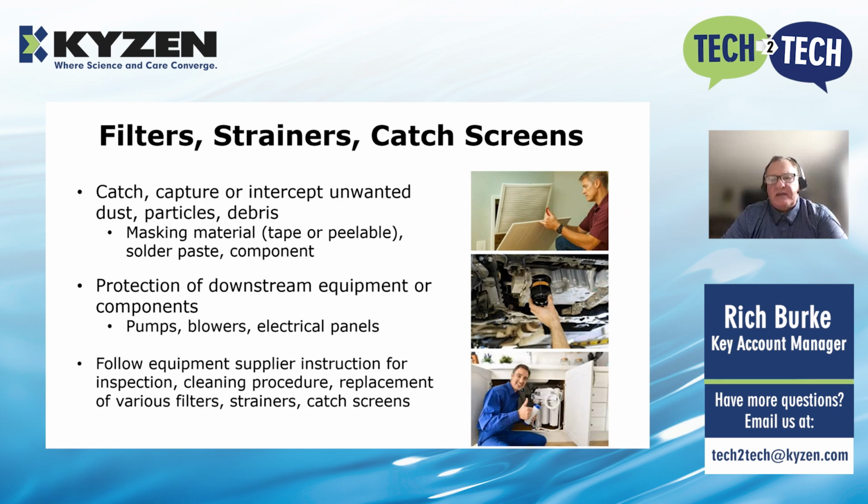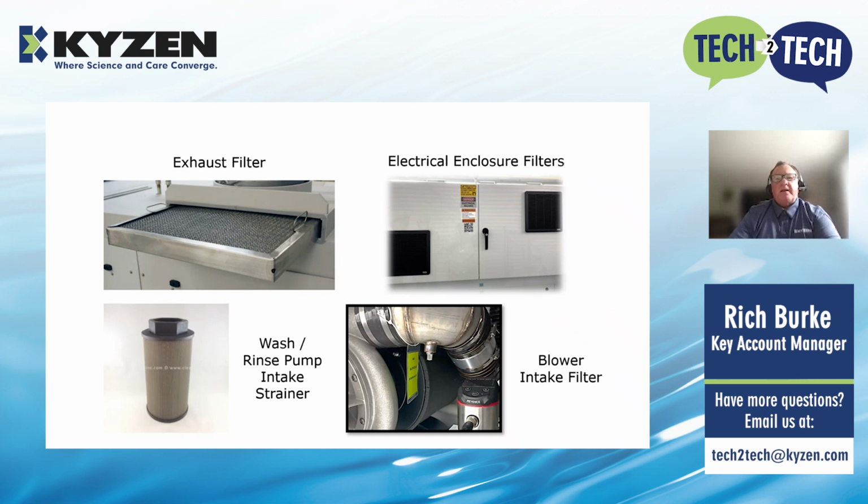So it's really a mechanism to protect our downstream components, and that can be our pumps, our blowers, electrical panels, ventilation system, for example. So, what I would say to this is follow the recommendation from our equipment suppliers in terms of the frequency and the processes and procedures for actually cleaning or replacing our filters and strainers and catch screens. Here are some examples of where we might find these within our system.